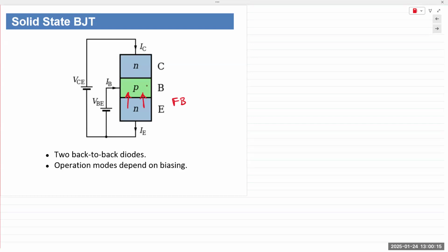Well, then we apply a positive voltage at the collector, and negative with respect to the emitter. And so when we do that, the electrons, some of them recombine with the base, but the majority of them cross over into the collector, attracted by the positive charge of the external supply voltage. And so it does not behave like a true PN junction diode. The second, the collector-base junction, I mean.